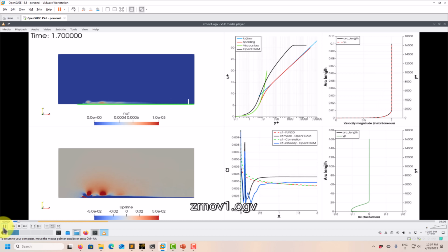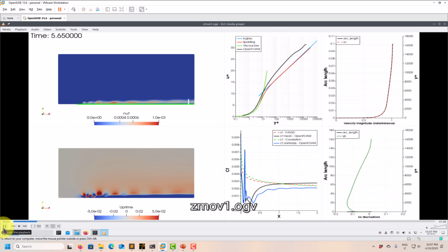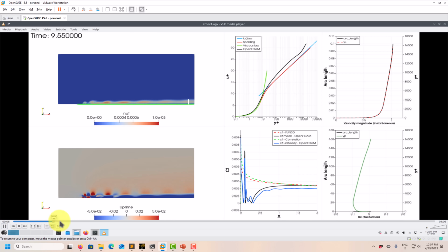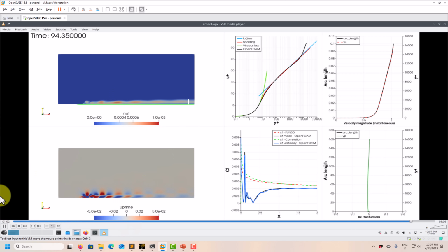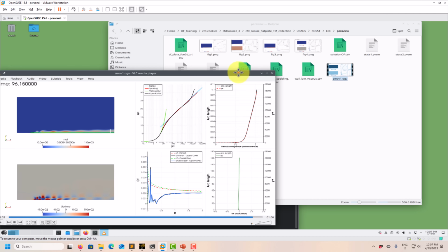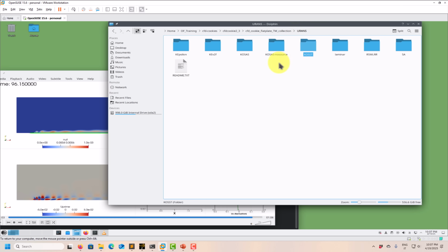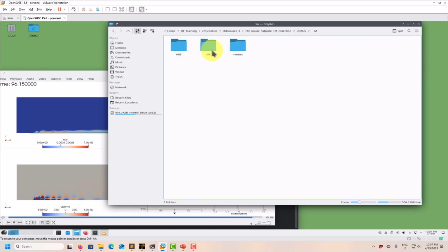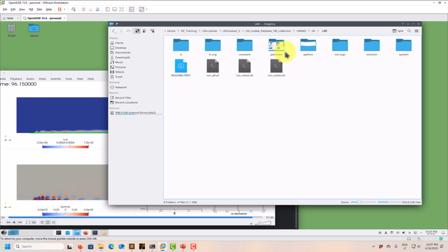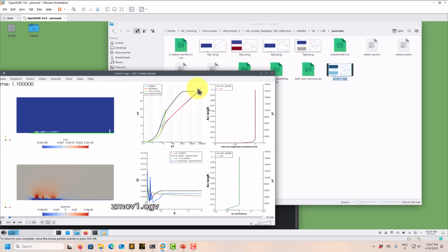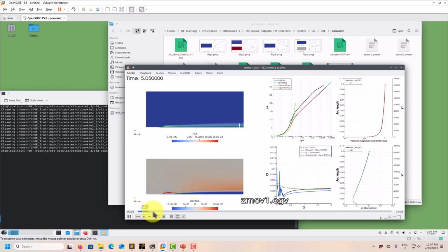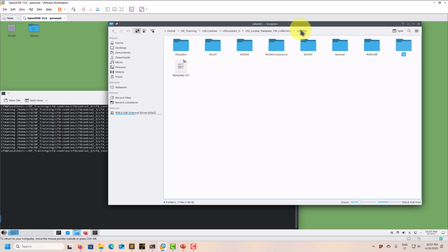Okay, so this is Spalart-Allmaras wall resolving, and look at that. It's not dissipating any energy there. And to stress this and to bring it back, what was one of the cases, Spalart-Allmaras. Okay, I forgot the Reynolds stress actually. Yeah, I need to address that one. And you put this one and look at that, this one, you let it run and then it's dissipating. So I would expect something like the K omega SST, but it's happening here, that situation, but you shouldn't be afraid of that.